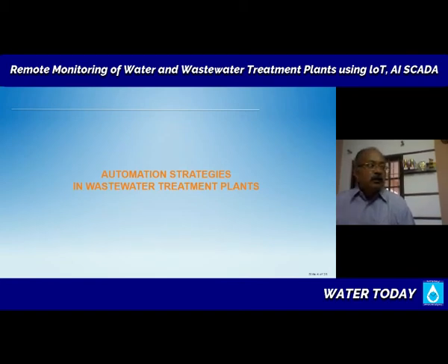Nitrate, ammonia, these things may matter in certain specific areas. Like, if you are in a textile industry area, then you have certain types of pollutant that you want to monitor. Not everywhere. So if you are talking about municipal wastewater, not industrial wastewater, then a lot of these parameters need not be monitored online. They can be analyzed on a periodic basis, daily or some such.